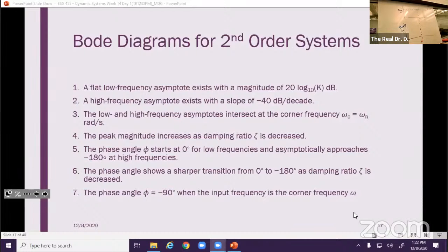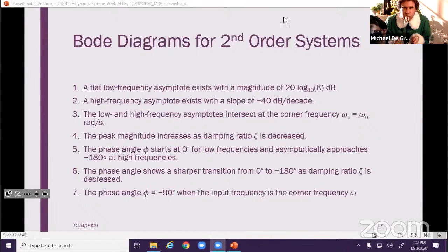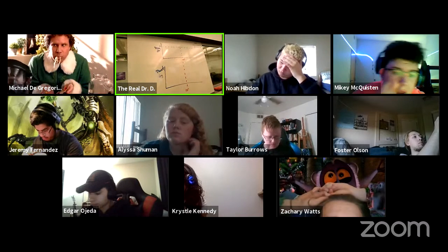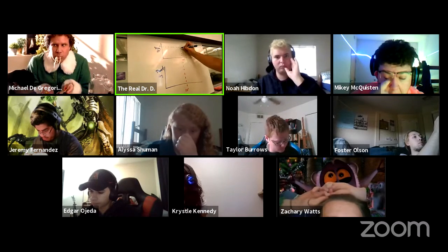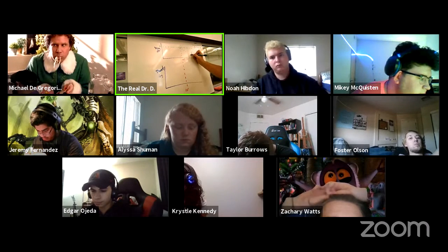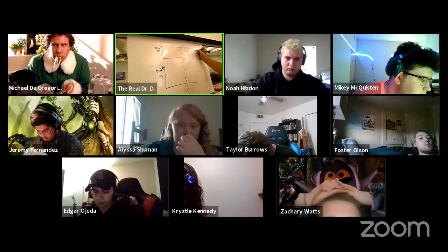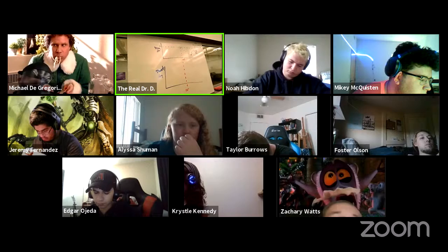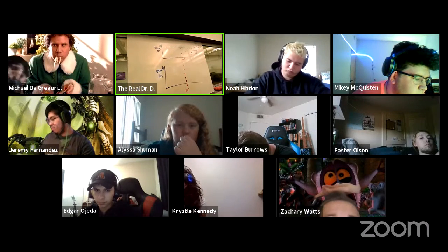In our case, we had 100 over s squared plus 4s plus 100, and omega n is the square root of 100, which is 10. Since that's our corner frequency, we have a line of slope minus 40 dB per decade.